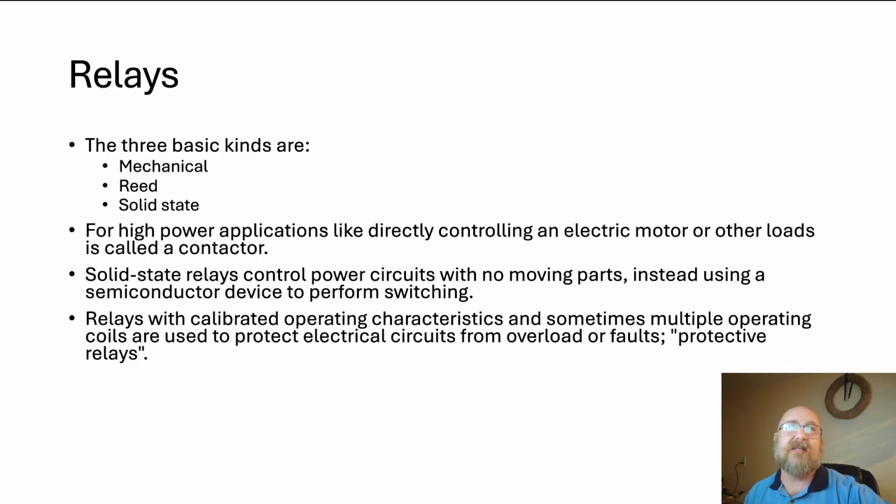Solid state relays are different than this. Solid state relays are not inductors. They are using semiconductors instead to perform that switching, so they don't fall within this. Reed relays are for relatively small amounts of energy, and they essentially use the magnetism between fairly flexible contacts to close or not close.